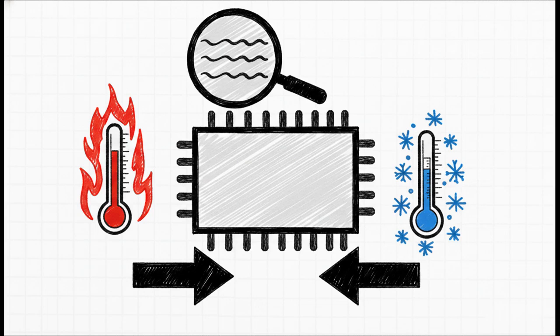Let's dig a little deeper into exactly why this happens. First off, you have temperature gradients, where the left side of your chip might be 30 degrees Celsius and the right side 33 degrees, subtly altering carrier mobility. You have oxide thickness differences. If one transistor gets a slightly thicker oxide during growth, its current changes. Then we hit the advanced physical effects. Take the well proximity effect, or WPE. When energetic ions are implanted to form the well, some of them scatter off the photoresist edge and implant right into the active area, permanently changing the threshold voltage of devices closer to that edge.